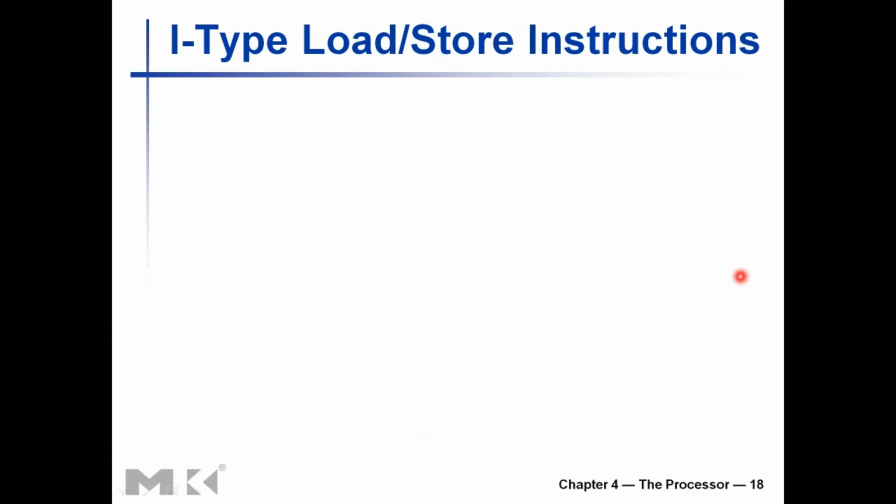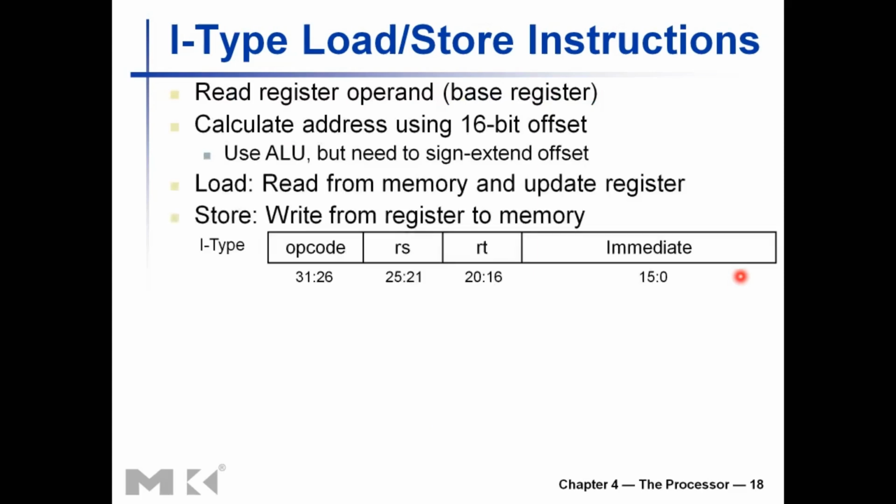Right, so next are I-type load and store instructions. Instructions that deal with memory, reading from memory and writing into memory. So, that is the format of the I-type instructions. First you need to read the register operand, that is the base register.